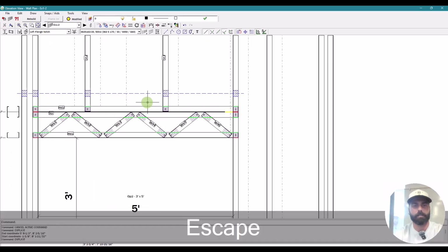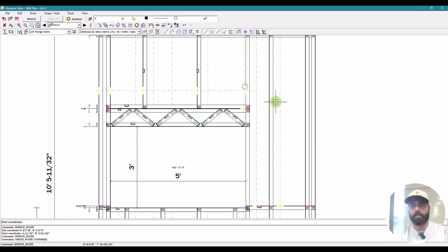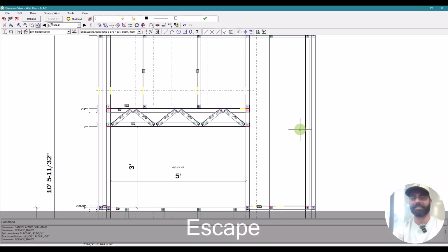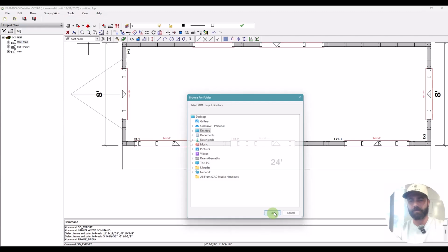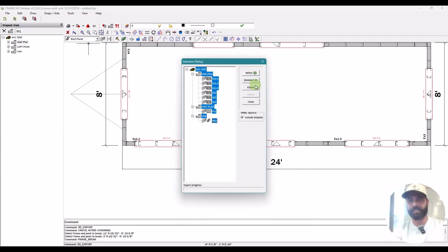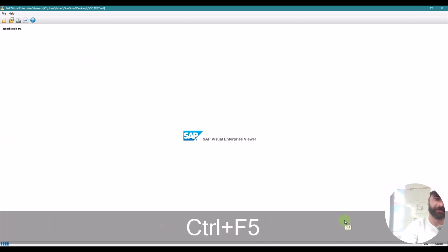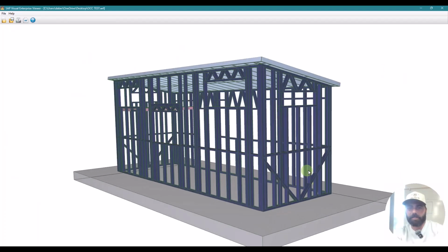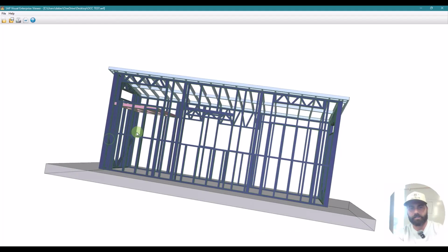But yeah, you can see all of our nogging is around the entire project, right? We would have added that 8-foot nogging here, so they have multiple levels. You got that 4-foot nog, you got all your deadwood studs, here's that guide, so you can see it catches the end. So if you had 2 guys working on this project, you could line up with that back wall and that side wall at the same time, and that speeds up assembly and it makes it perfect so the guys aren't pulling out a tape measure and having to align it. They're relying on the machine accuracy.